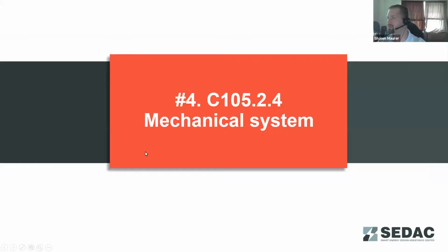We did have one more question come in before I move on to mechanical systems about for refrigerant lines outside the building, is a jacket required? Yes, you do need to have on refrigerant lines some kind of UV protection for that foam insulation. That's probably the most common degradation we see, is that UV causes that foam to dry rot over time and then it crumbles away. Usually what we've seen in the past is a paint on UV protectant for that foam insulation instead of a jacket.